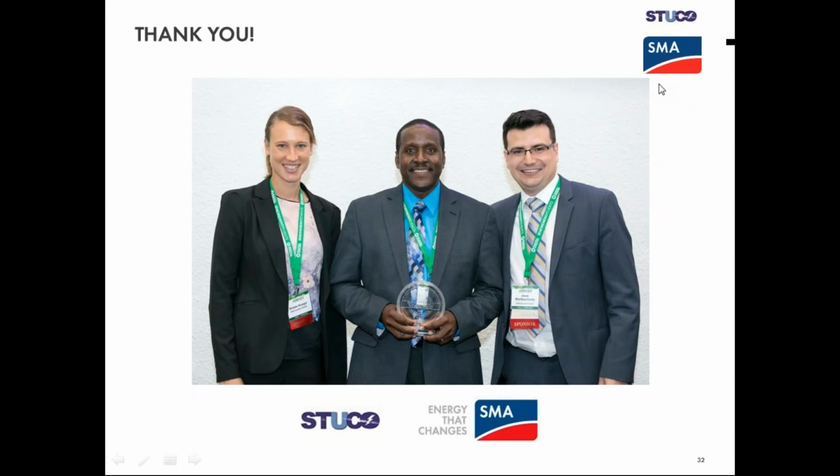They have a performance warranty of 10 years, and the simulated lifetime is between 12 and 15 years. So the lithium-ion battery has a calendar life, and aging depends on many key performance indicators. So we are closely looking at them, and we have defined with the manufacturer, Samsung SDI, a so-called operation window for all of these key performance indicators.